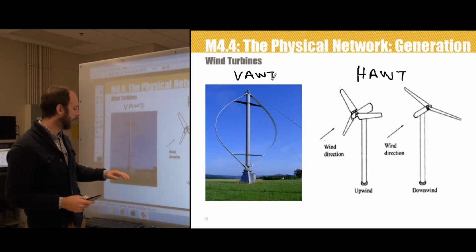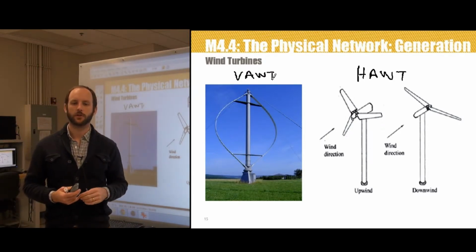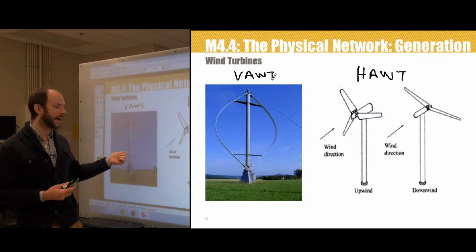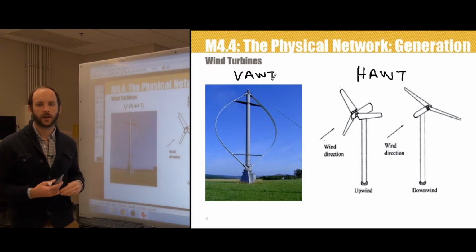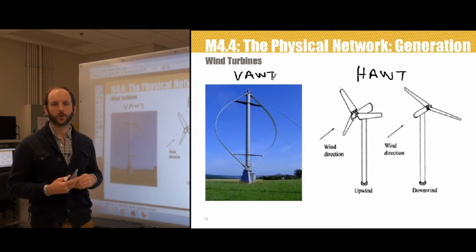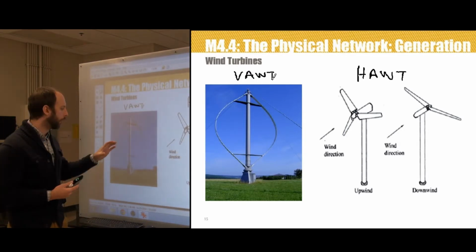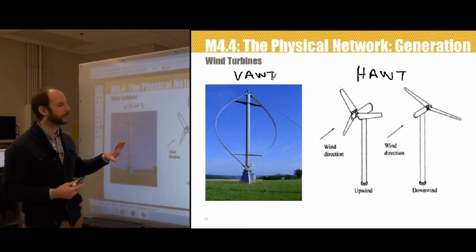Unfortunately, the design advantages of reduced costs at the bottom and constant tension, making the blade design a little bit more simple, are overshadowed by the major disadvantage of the vertical axis wind turbine. The blades have to be located near the ground where wind speed, and thus available wind power, is lower than at high altitudes, and prevailing winds are more turbulent and less predictable in duration and speed at low altitudes. So, although this design works better, the characteristics of wind at the surface of the Earth are less desirable to produce electric power, and we don't use them very frequently at all.